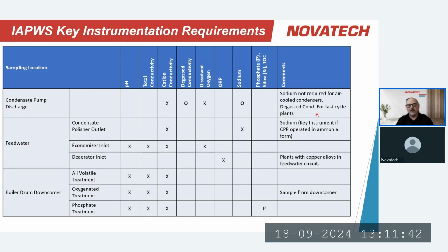I mean a plant, for example, that may be running at a lower setting and is asked to come up on demand, such as a peaking power plant or something of that nature. There's tremendous economic benefit in being able to start up the plant more quickly, and measuring degas conductivity can allow the operators to do that.